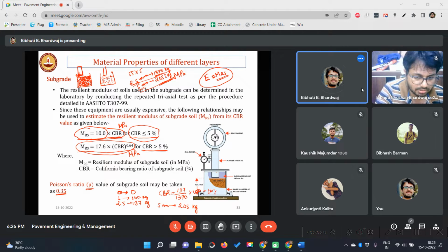Have you understood? Yes, sir. Okay, so that's what CBR is. It is a very simple test. I think you also have a setup in your lab. You simply take some soil and prepare the mold using the modified proctor method.